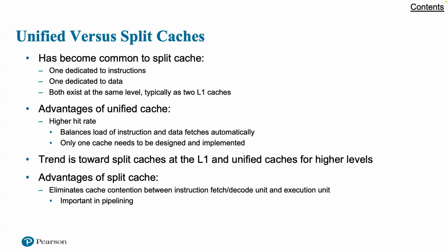This is important in any design that relies on the pipelining of instructions. Typically, the processor will fetch instructions ahead of time and fill a buffer or pipeline with instructions to be executed. Suppose now that we have a unified instruction/data cache. When the execution unit performs a memory access to load or store data, the request is submitted to the unified cache. If at the same time the instruction prefetcher issues a read request to the cache for an instruction, that request will be temporarily blocked so that the cache can service the execution unit first, enabling it to complete the currently executing instruction. This cache contention can degrade performance by interfering with efficient use of the instruction pipeline.